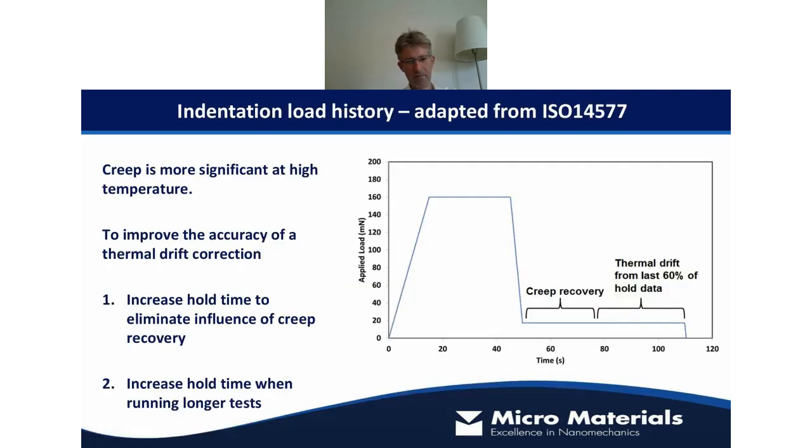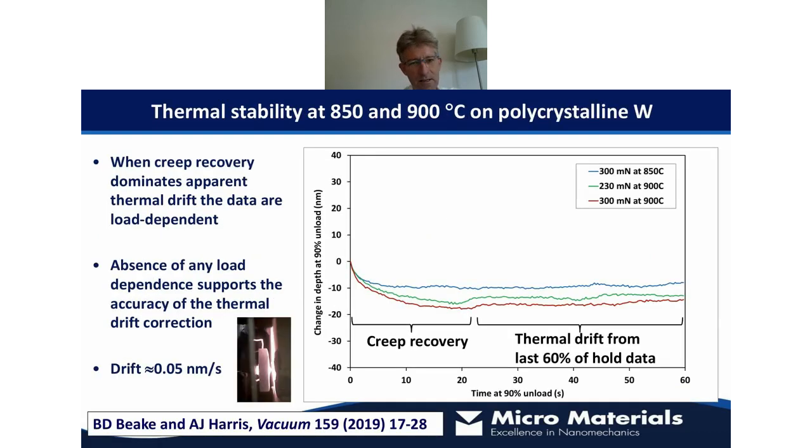So if I go back, we're looking at the depth, what happens in the depth while we're holding at 90% unload. So this is just analogous to what we do in ISO 14577 at room temperature. And this is just trying to understand and convince ourselves that we have minimal thermal drift. So what you can see typically in a hold period like that